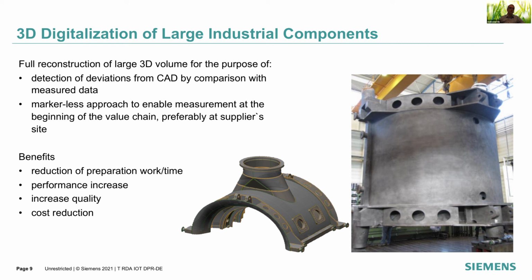At the time we started the project, they were using photogrammetry markers. They just paste the markers on this huge model, take a lot of photos, do the optimization, and then get the precise, accurate positions of these markers. But this is not good enough, because it takes hours to put these markers on, and it's done manually. Second, it's sparse: you put markers only in certain locations, so you cannot densely reconstruct the whole thing and have a complete assessment of the model.